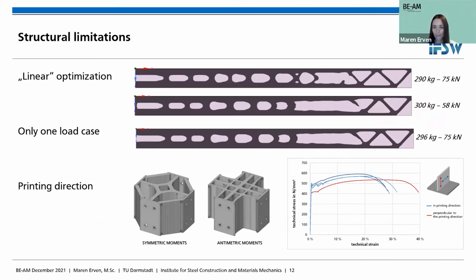And that leads me to the first limitations. The optimization I use can just think about linear problems. So that means we have no yielding, no buckling, and no nonlinear bearings. And here on the right, we can see what that means. Here are 3 results for the same mass restriction and actually the same load, but the second result has a significantly lower payload than the others have. But the algorithm would say, okay, they're actually equal to each other. That's because it doesn't focus on nonlinearities.